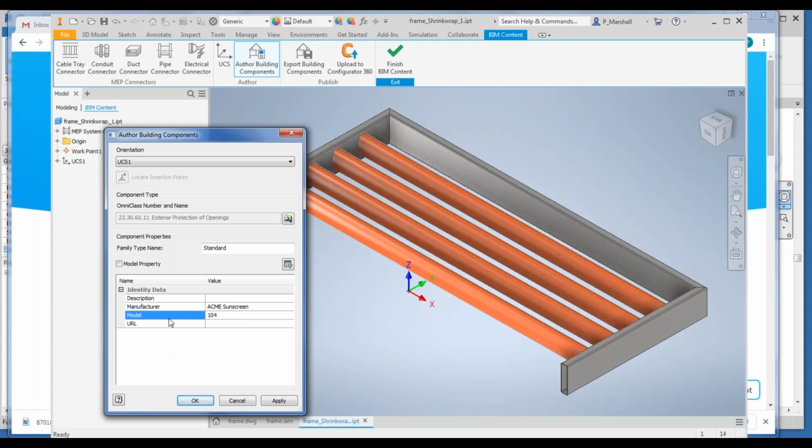All right, we could put other properties in here too. We could put in finish, materials. You could put in weights, center of gravities, because Inventor knows these things, of course. So it's easy to transfer them over to Revit. And again, this might be useful in your BIM model.